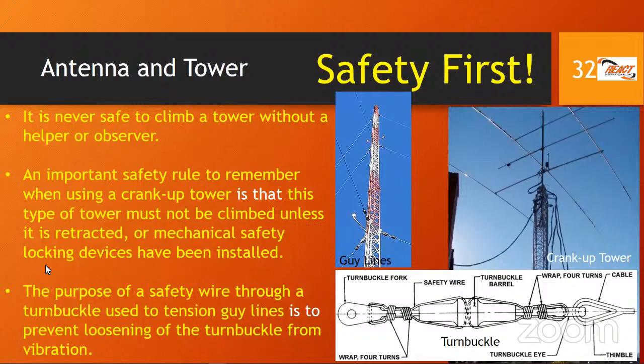All right, so a couple of bullet points that we need to be aware of in terms of our antenna and tower safety. So first of all, never, ever climb a tower without someone else being there, called an observer or a helper. Do not do it alone. Never do that, and that's an exam question.